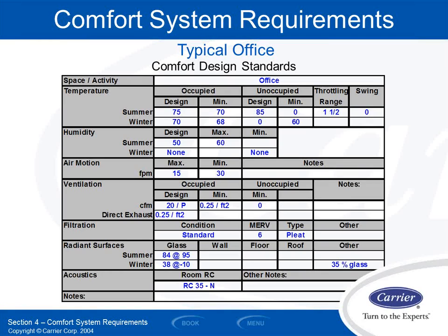What can I do not to go to high fire, basically? So you set it back for 60 degrees in setback mode for heating. It may hover you at 67, 68, and now let it go all the way back to 60 because it knows that's what it needs to do on a day like today with the current weather conditions to not have to go to high fire tomorrow morning and get you the most savings possible. Right? But in general, for most equipment, single and two-stage equipment, you want to set it back as aggressively as you can as long as you still have time the next morning to heat up all the surface temperatures before people complain in the morning.